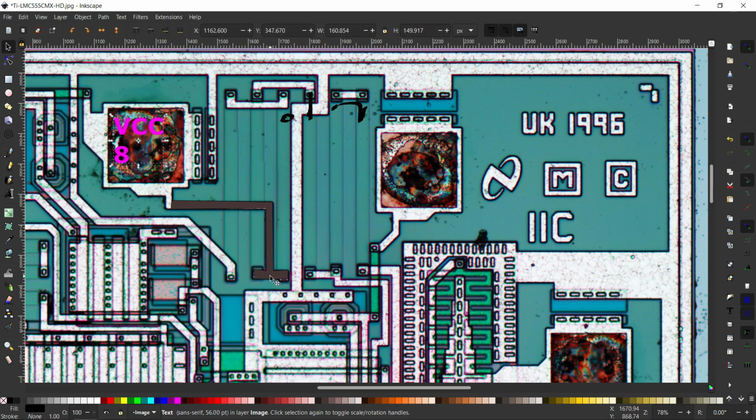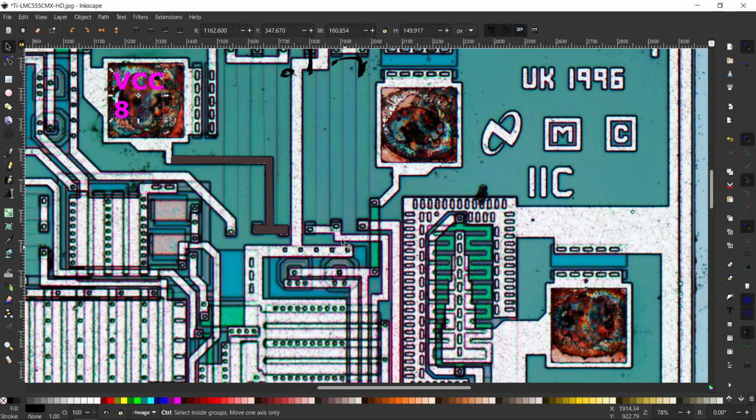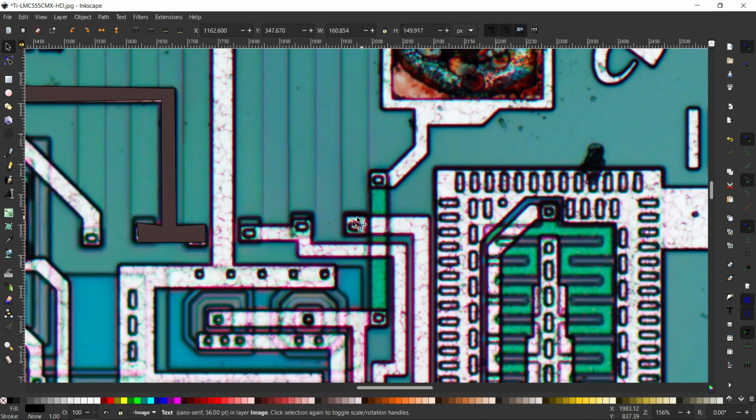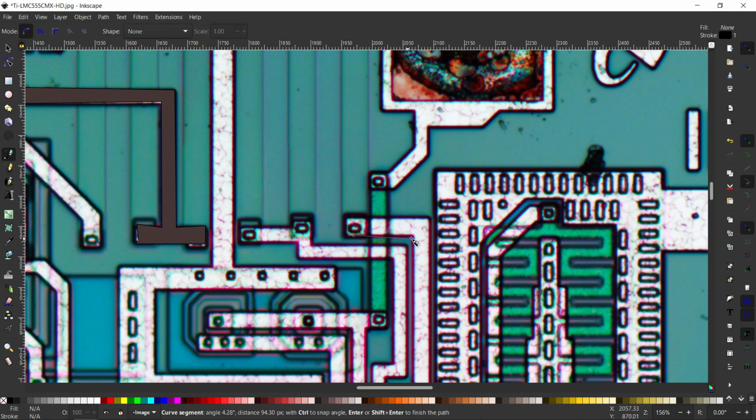So let me trace out the other net of the resistor, because the other net of the resistor is connected to the ground signal. This is where the resistor starts, because this is where the junction is starting. So let me trace where this pin is going exactly.